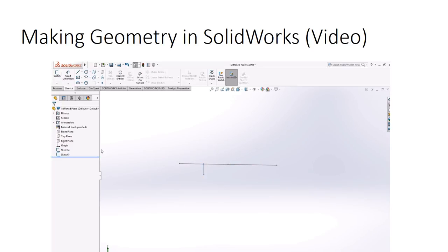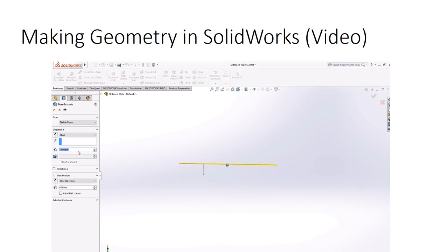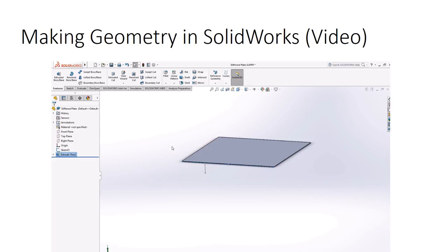Now I'm going to be doing extrusion. So I pick first sketch 4. Did extrusion. Picked 1,000 millimeters. And I like to go to the reverse direction always. I don't know why, but that's just a thing. And I added a thin feature and made it 6 millimeters. So that's going to be the thickness of our plates.